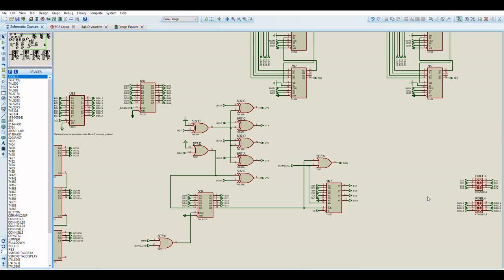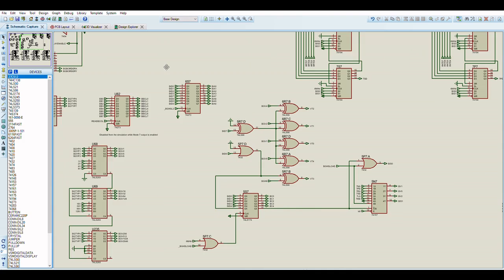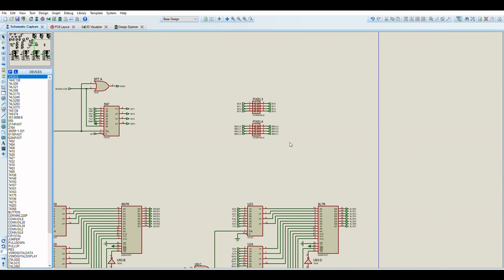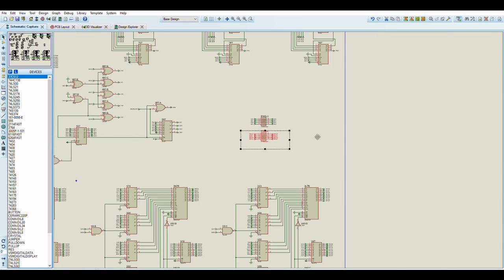But what does the final pixel combination of all of these layers is the next layer of the board. So the tile board has the ability to set, at any point during the screen, a full 8-bit pixel color and latch it. There is no RAM contention or anything like that. This allows us to create a very fast way of updating the background color, and this updated background color information is output to the pixel 4 header here.